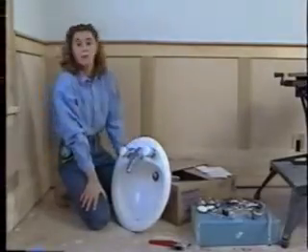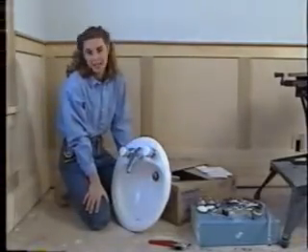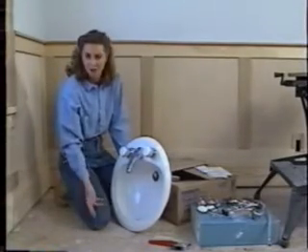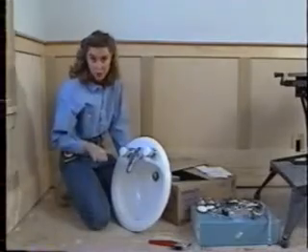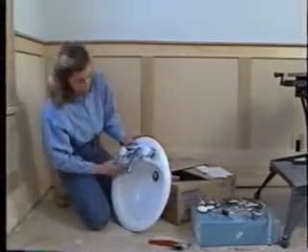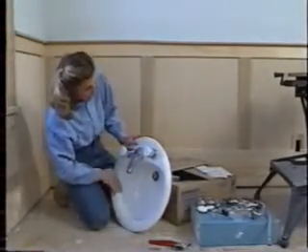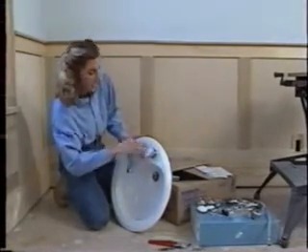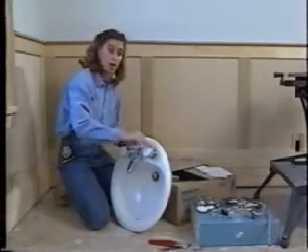There's not a whole lot of room in the master bathroom, so we're setting up the sinks and the whirlpool here in the bedroom. Besides, it's a lot easier to attach the faucet and the tail pieces before the units go in place. Now this sink is made out of vitreous china, and on this model we've got 3 openings, for the faucet and for the control handles. And the control handles are 8 inches apart.